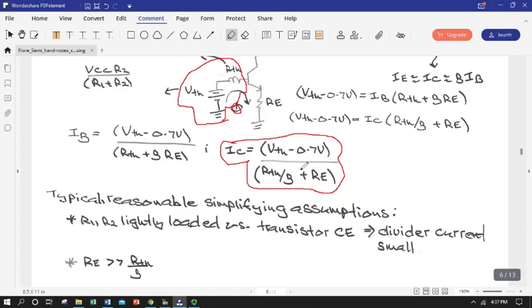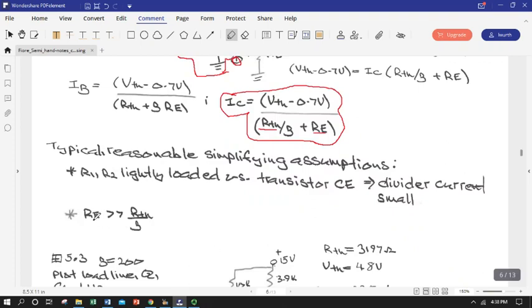So now if I wanted to determine whether or not that collector current was beta independent, I would compare the values for R Thevenin to R sub E, and if they were similar, in other words if R Thevenin wasn't like 2 or 3 orders of magnitude bigger, I could say I was beta independent and say that R sub E is much bigger than this. Probably is, because beta is going to be at least 100.